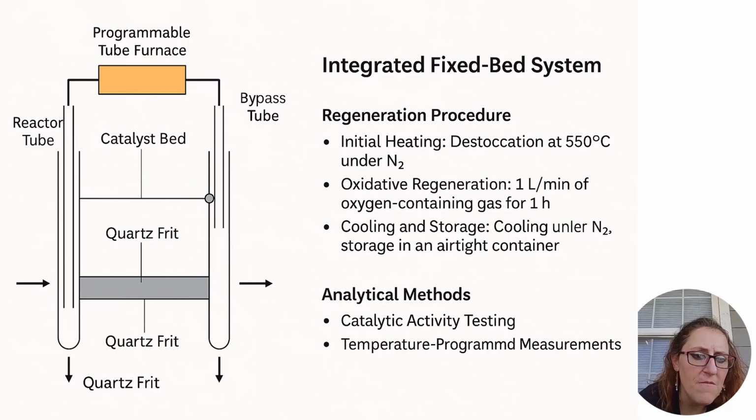Proper control of heat flux prevents thermal runaway, maintains uniform reaction temperature, and ensures kinetic data accuracy. Reactor insulation and flow balancing are therefore essential in industrial designs. Future catalyst pellets may integrate thermally conductive additives like silicon carbide or aluminum nitride to improve internal heat transfer and prevent local overheating, thereby extending catalyst life.